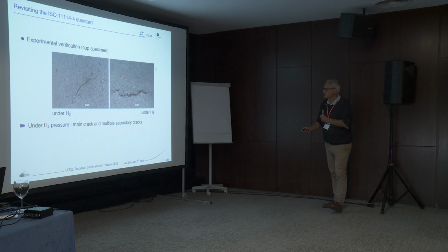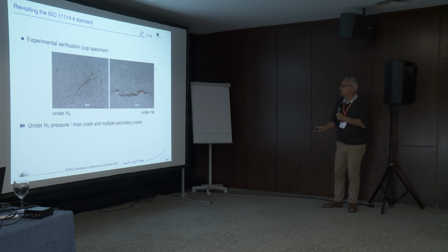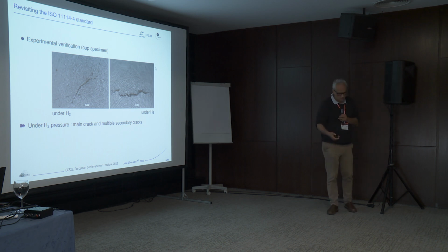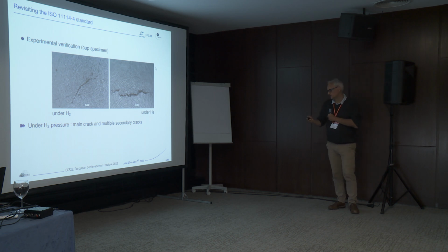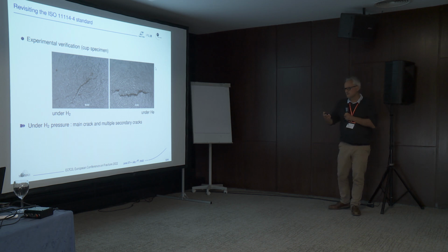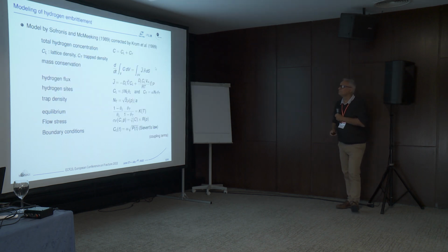And that's what you get under helium pressure, just a main crack, and that's it. And that's pure ductile failure. So we think that the design is working, and we are going to use it extensively to test hydrogen embrittlement with better condition, better loading condition, so that the analysis is much easier.